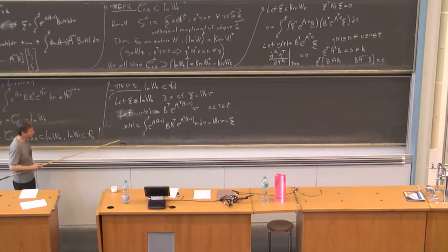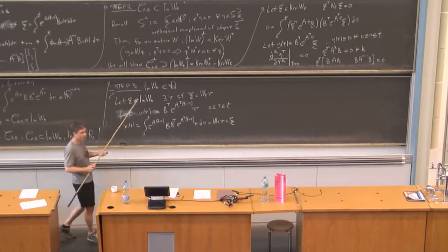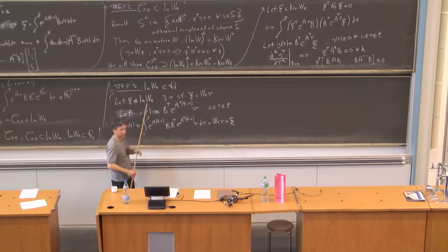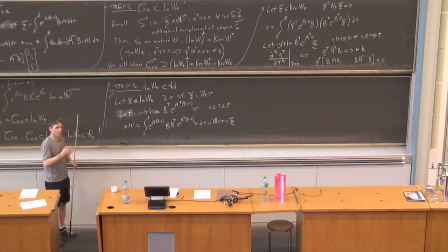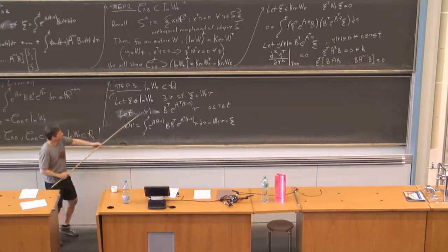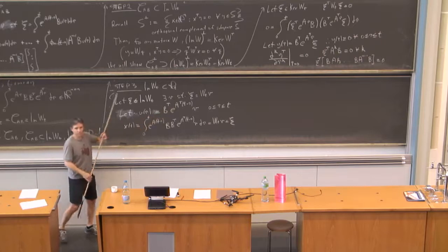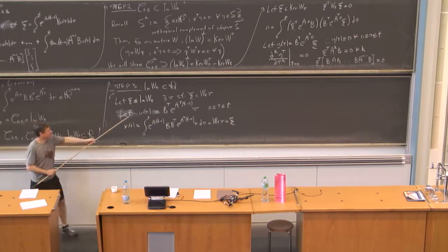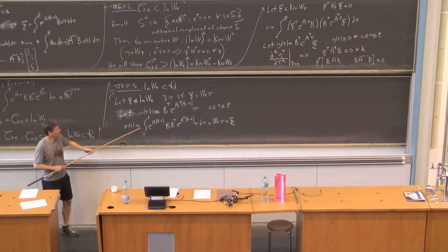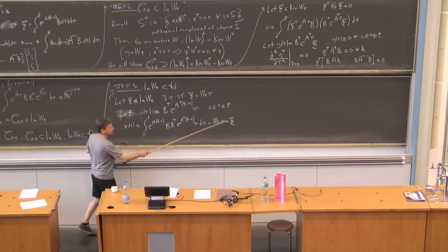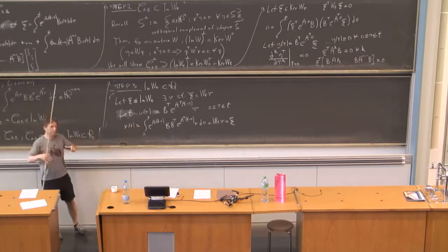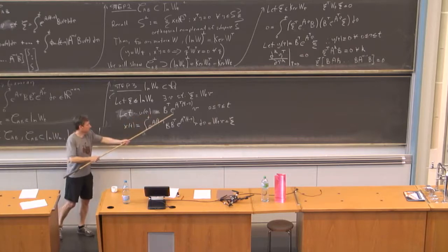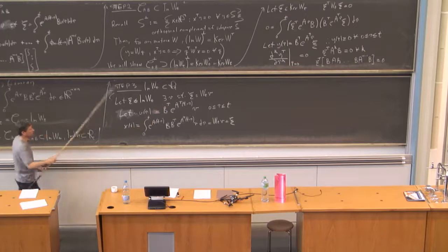And the way you would prove that is you would define a controllability operator in the Hilbert space L2, and you can show that basically this thing that we created here is a projection. So basically, out of all the U's that drive you to the state, if you feed that through a projection, you will get this special U. So that's why it's the minimum energy. So this is a nice connection to all of this.